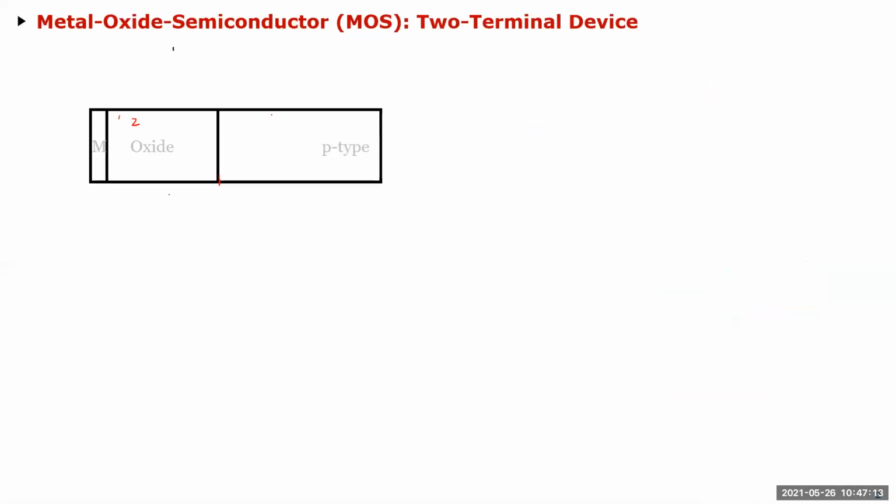Before we went to the 4-terminal devices, like I said yesterday, we went with just the MOS structure, just to calculate the threshold voltage. What are the parameters responsible for turning the channel on and off? Because that's essentially what we're trying to do. We're trying to create this 3-terminal device, where we can control the resistance between 2 terminals by controlling the voltage on the 3rd terminal, which in MOS is a capacitive one, which is ideal for low power application. That's the whole idea of how people moved from BJT to MOS, because in BJT you always have a base current. Here you don't have that DC base current.